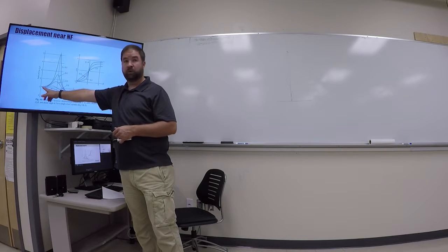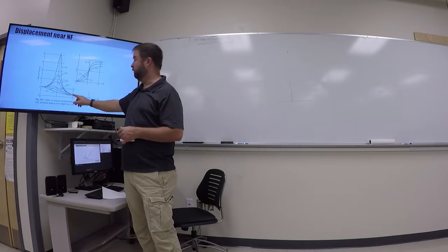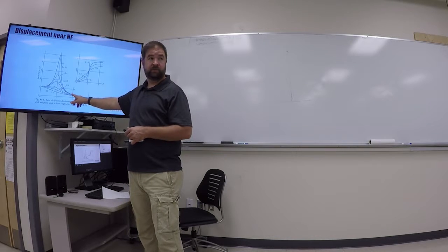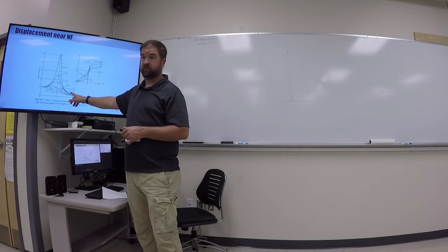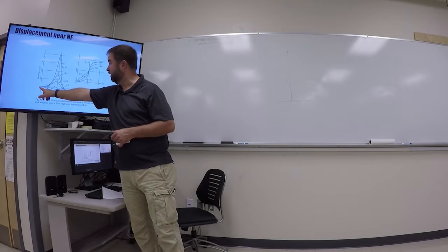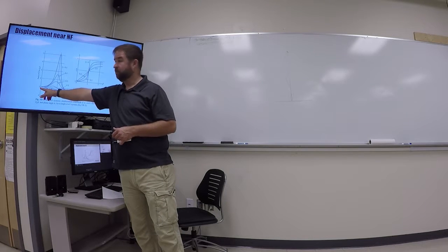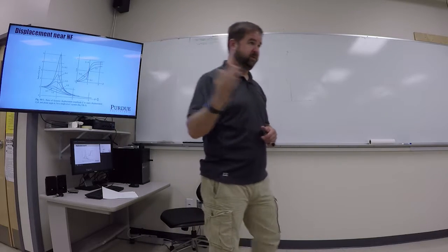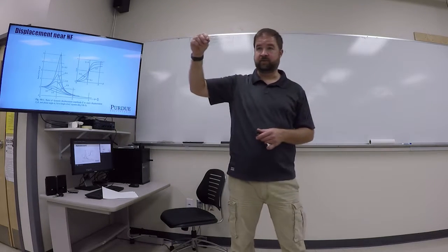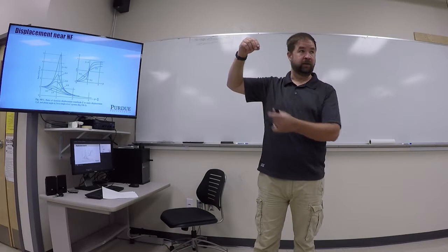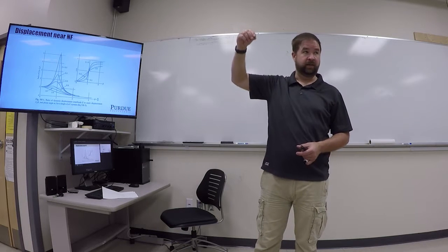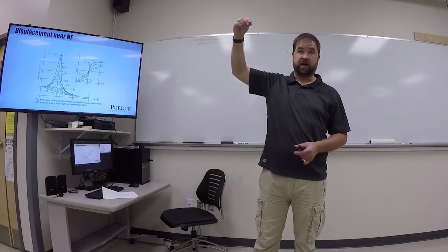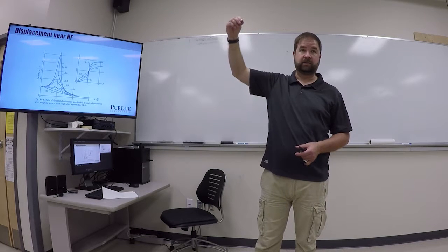When we're lower than natural frequency or above natural frequency, we have reduced amounts of response. So if my input is 1, when I'm at really low frequency, I get a displacement of 1. If you think about that, if I have a mass hanging from a spring and I move it really slowly, the spring doesn't really stretch and it just moves up and down, right?